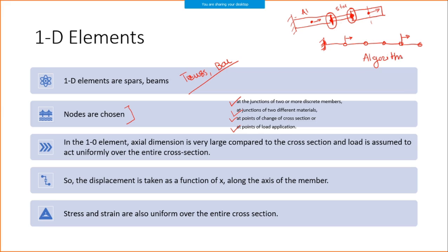These algorithms identify the locations where you have applied forces on the model, and based on that, they automatically put nodes at that particular location. Sometimes in some FEA solvers or tools, you might have seen a warning or message saying, "I want to convert the load points into nodal points." So this is what happens.